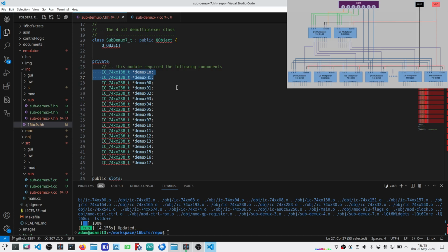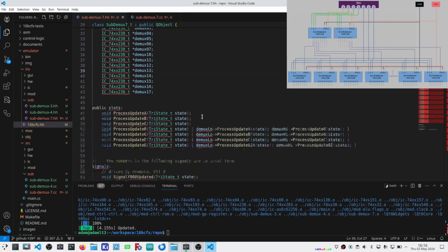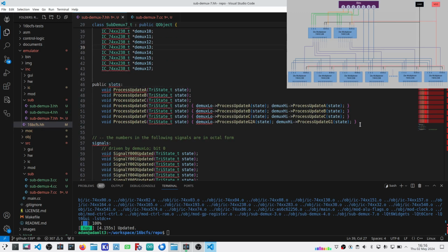It doesn't hurt. There's no difference in the way that they function other than the polarity of the active signal. So I can tie the outputs of the top level of the tree to an active low signal, and I've got 2 of them on each of these 74HC238 demultiplexers here. Other than that, I've got 7 bits of input.